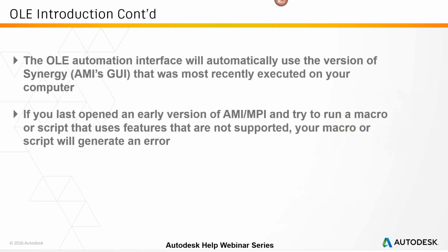Now, continuing on that, the interface that the OLE uses is usually the first version of Synergy that you bring up. So when you launch Moldflow, the GUI that comes up is called Synergy, and the one that was most recently executed on your computer is the one it normally utilizes as a first pass. So if you last opened an earlier version of AMI, maybe you're not on 2016, maybe you did 2014 or 2015, it would utilize that.